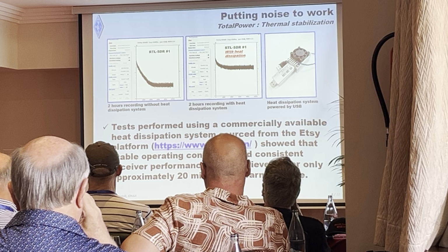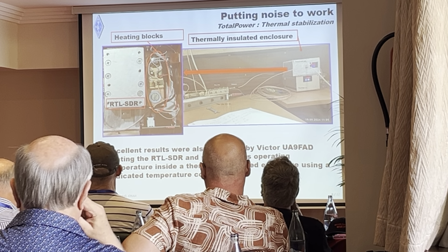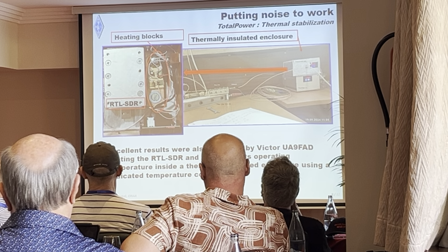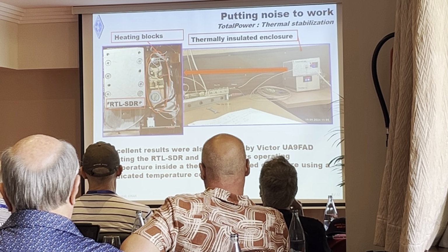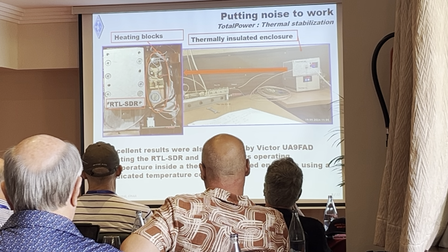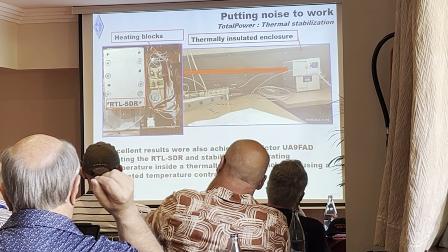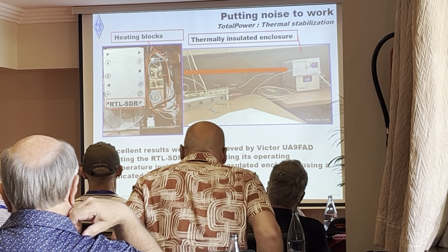The other solution comes from Victor, UA9FAD. I think that most of us know this guy because he's very, very active on the band. Very good signal. He actually put the RTL SDR into an aluminum box. He put a heat sink with a regulator and everything inside a thermal-insulated enclosure.